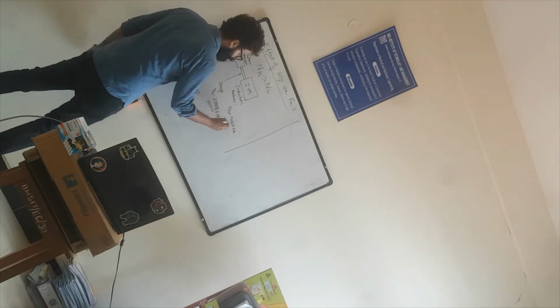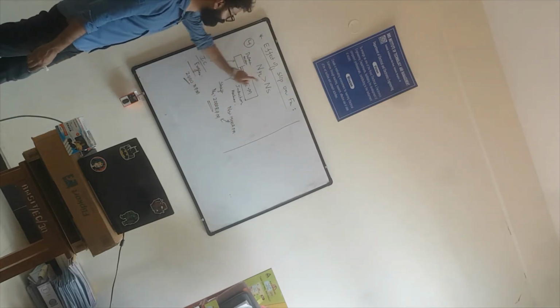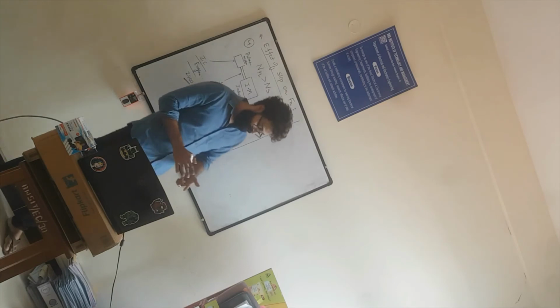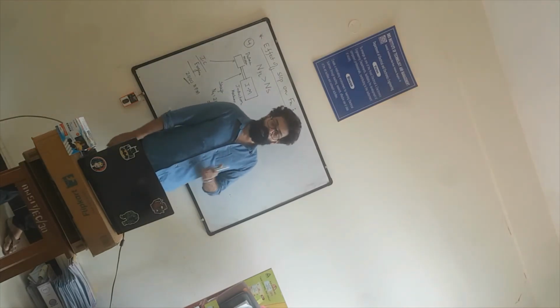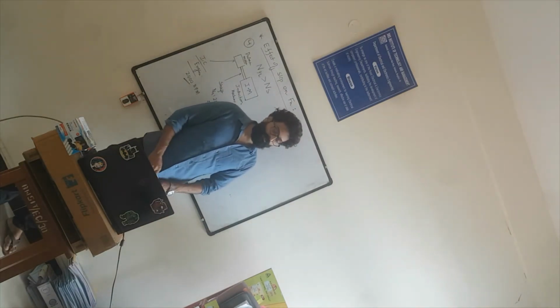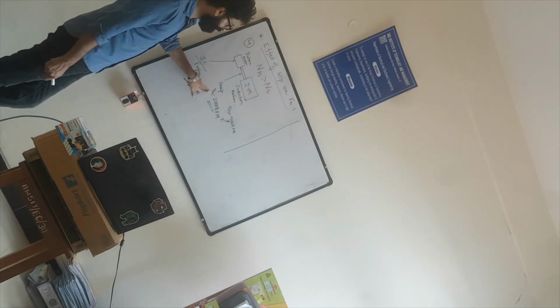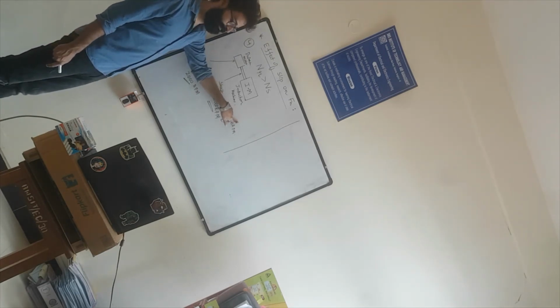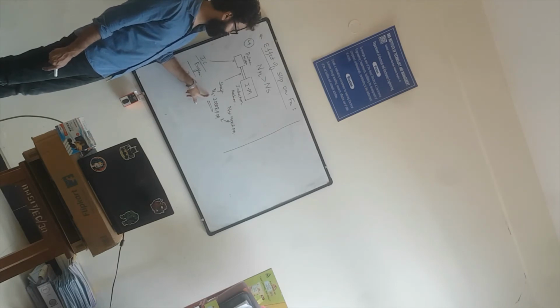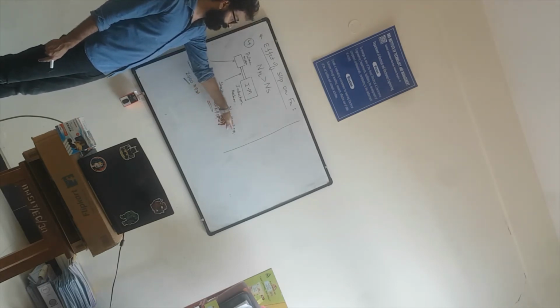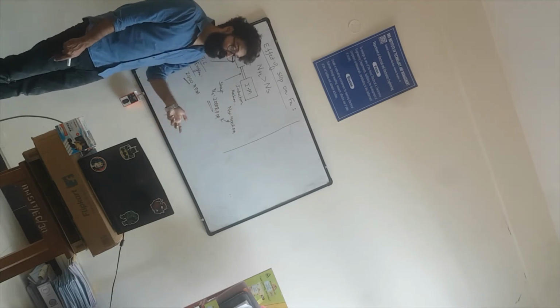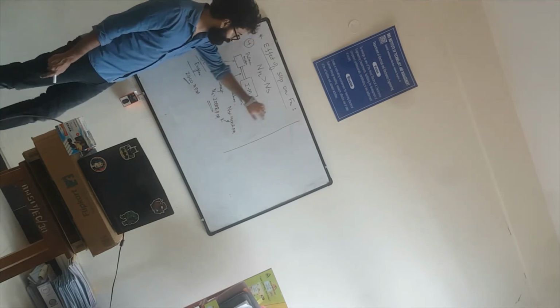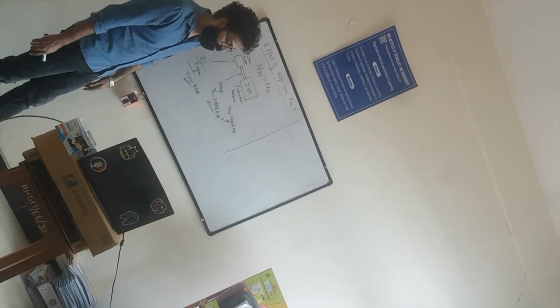Now you compare the NS value with NR. NR is greater than NS. This is what is done while producing electricity. Basically, the mechanical energy is overpowering the electrical energy. Mechanical rotations are overpowering the electrical rotation, because NS is produced when you connect the electric supply to the stator winding of an induction motor, right?